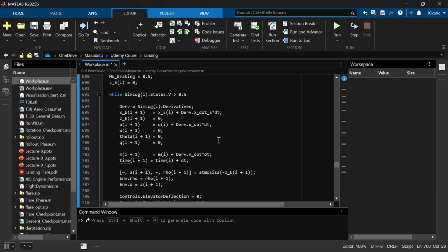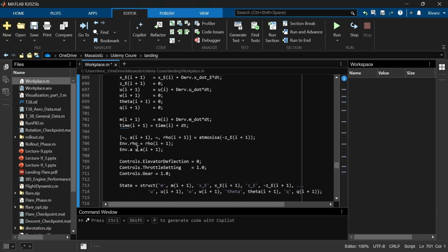Here, this is another strategy that we can apply. This also prevents the while loop from calculating those differential equations again and again and again. It simply assigns 0 and passes them. This increases the speed of the simulation, but I don't know how this affects the whole simulation when we consider the whole mission profile. But this way is also acceptable, and we can clamp those states to 0 conveniently. So let's scroll down.